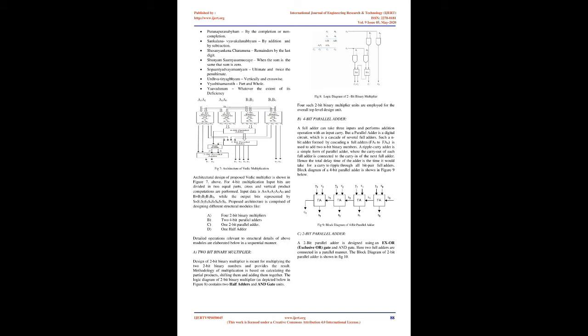F. Sequential multiplication algorithm. Sequential multipliers are mostly preferred because of their low area requirements. A sequential multiplier multiplies two binary numbers, multiplicand of n bits and multiplier of m bits, using a single n-bit adder. Firstly, the circuit processes a single partial product at once and repeats it m times. Figure 6 below shows the partial product generation and addition in a sequential multiplier. Fig 6, example for sequential multiplication.